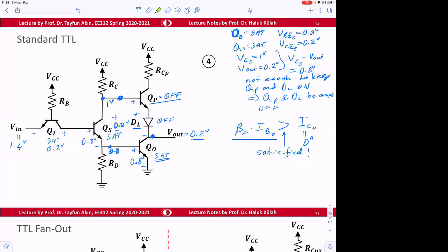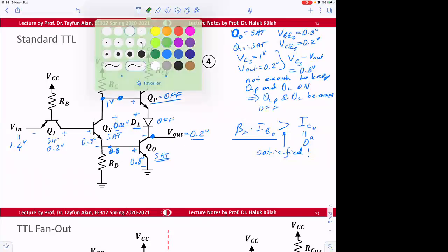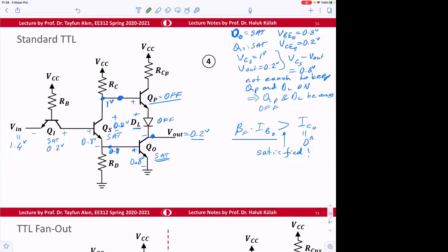As I told you, if we start questioning the values for those kinds of cases, so your question is 1.3 volt. What happens? This will still be 1.5 volts, but then this is going from forward active to saturation.